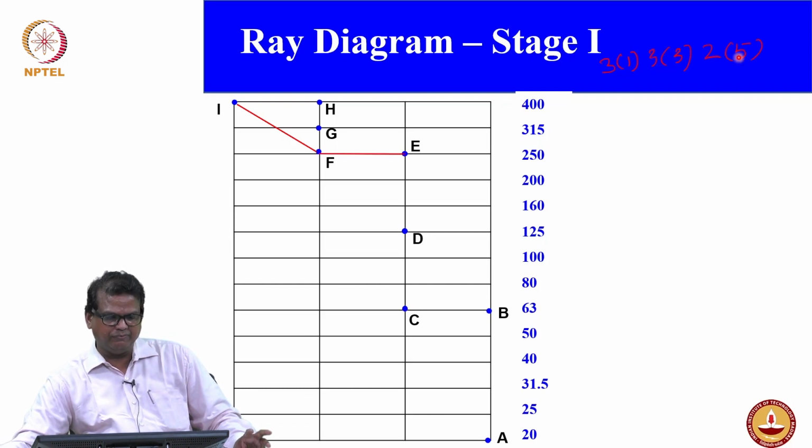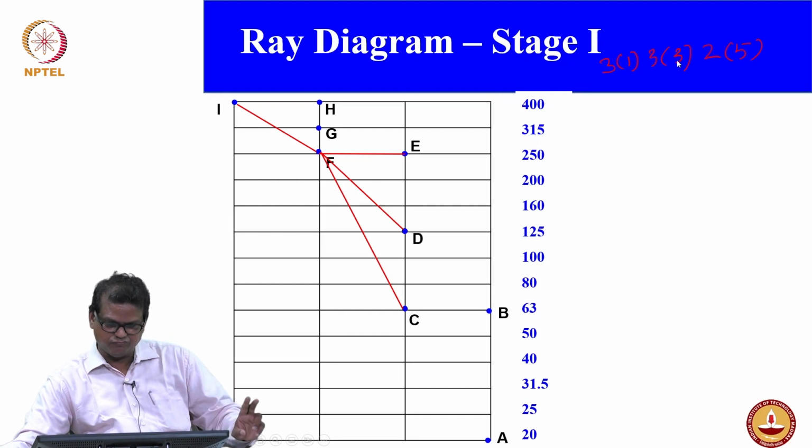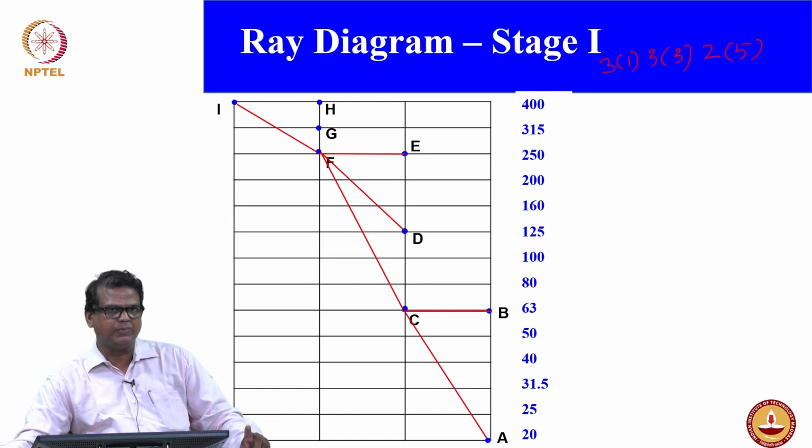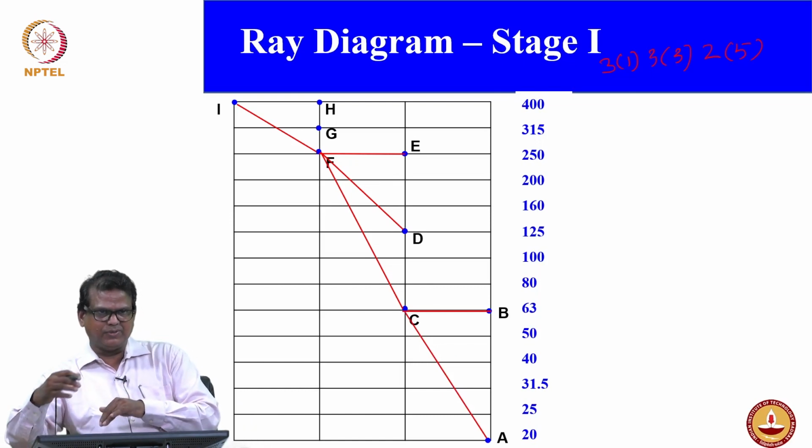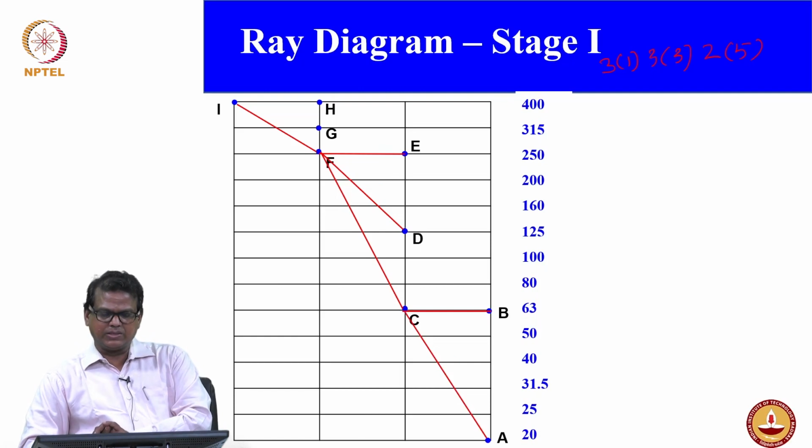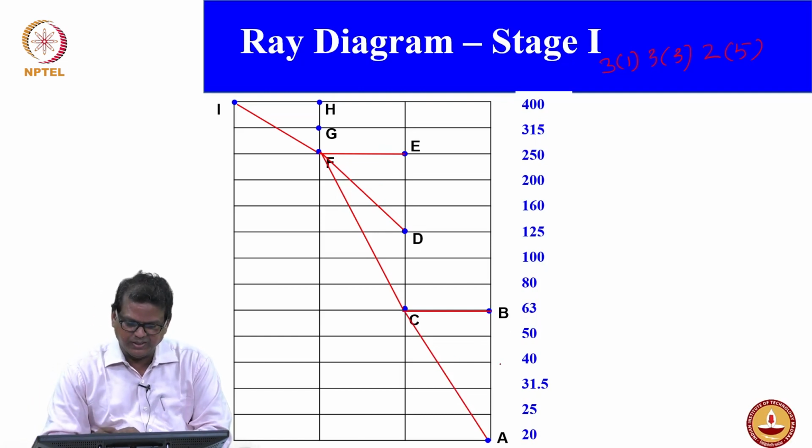Okay, I to F, F will give me again 3 things. From F we will have 3 output speeds. You can see that E, D, C is satisfied. For one input speed of stage 2 gives me 3 output speeds, which we have already. The next again will give me 2 output speeds of stage 3. The C would give me 2 output speeds, which are 5 step ratio apart, which is clearly given.